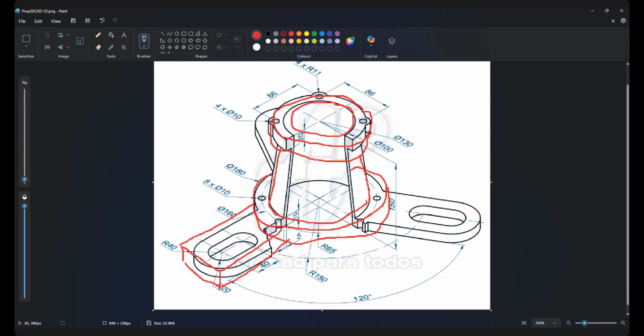Later we can do fillet. Later easy, we can do slot. I already showed you slot. Extruded, cut through all. Then you have this thing. Then you circular pattern, then everything is done. You just circular pattern this one.